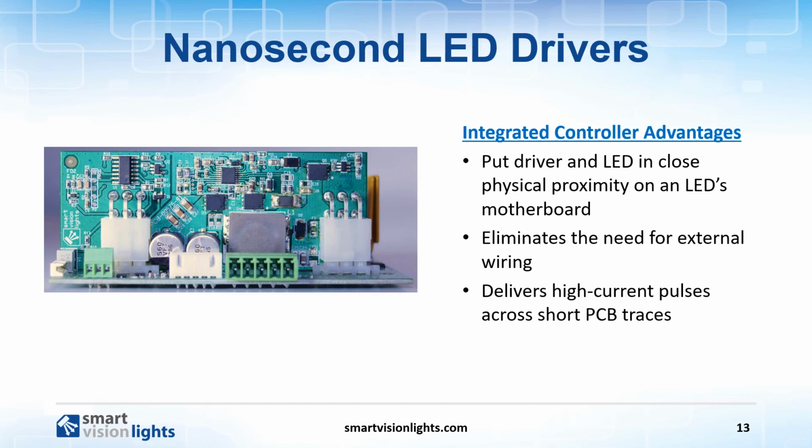With overdrive enabled for extreme brightness, even at a 10% duty cycle, such configurations are capable of 100,000 strobes per second. Additionally, faster on and off rates help compensate for latency issues during asynchronous operation, wherein a camera shutter is triggered by an external source, such as an approaching product tripping a photosensor.